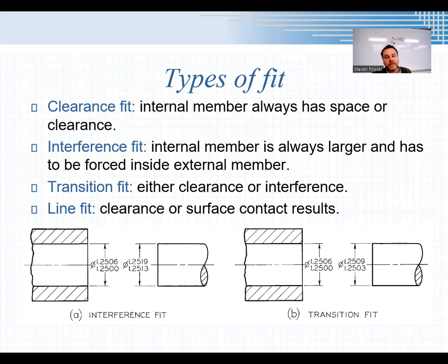An interference fit: the markers that I keep using as a good example because, well, it's handy and we've all probably picked up a dry erase marker before. This is what we call an interference fit. You really have to force that inside the other, right? And you want that tight seal because we don't want the marker to dry out. So you want an actual interference fit on something like this. That's where the internal member is actually larger than the external member. They're going to have to be forced together.